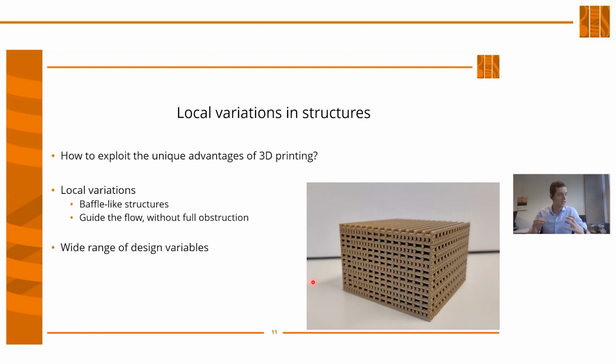It's a denser zone, so the gas is less likely to go through that. It would like to go around that. So the gas goes around it and inward, goes around it and inward. Getting this swirly flow, this cross flow, would really enhance the contact with the wall. And the nice thing is that because it's open, not a fully dense structure, the gas can also travel through it, so the pressure drop will not be as high as it normally is.